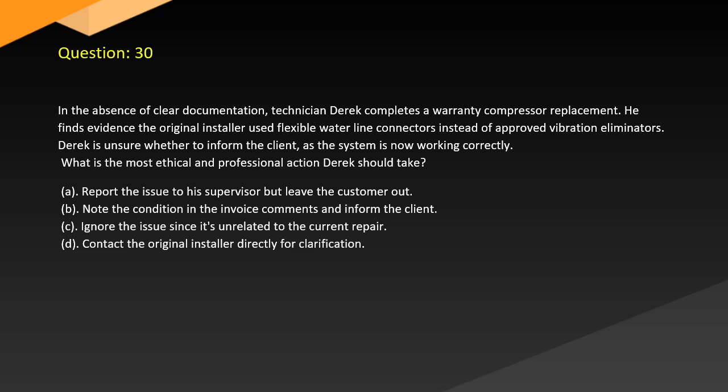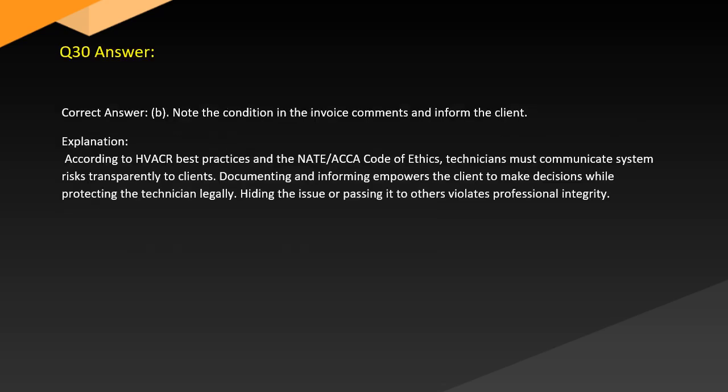Question 30. In the absence of clear documentation, technician Derek completes a warranty compressor replacement. He finds evidence the original installer used flexible water line connectors instead of approved vibration eliminators. Derek is unsure whether to inform the client as the system is now working correctly. What is the most ethical and professional action Derek should take? A. Report the issue to his supervisor but leave the customer out. B. Note the condition in the invoice comments and inform the client. C. Ignore the issue since it's unrelated to the current repair. D. Contact the original installer directly for clarification.